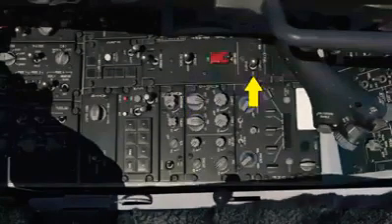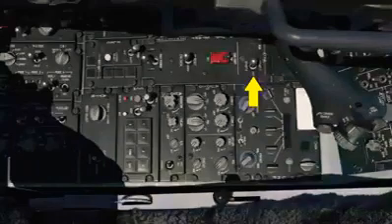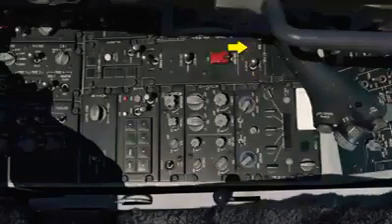At the top of the panel is a jet fuel starter switch with off and start 1 and start 2 positions that use one of 2 brake and jet fuel starter accumulators to drive the hydraulic starter motor. Using JP8 fuel, starter 2 should be used. Next to the switch is a JFS run light that illuminates within 30 seconds after JFS initiation.